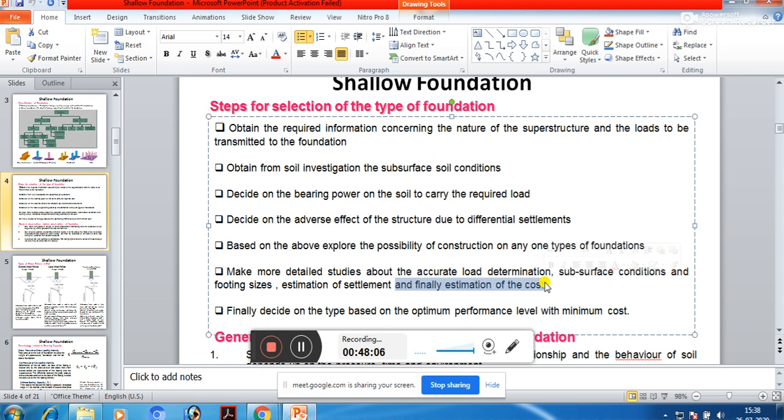So while constructing a huge structure, or any structure, ideally you must check for the soil condition. Subsurface condition testing is a must while doing any kind of structural construction. And without subsurface condition testing, one should not select a foundation, nor design a foundation, without getting the real data of the subsurface condition from the soil mechanics lab.